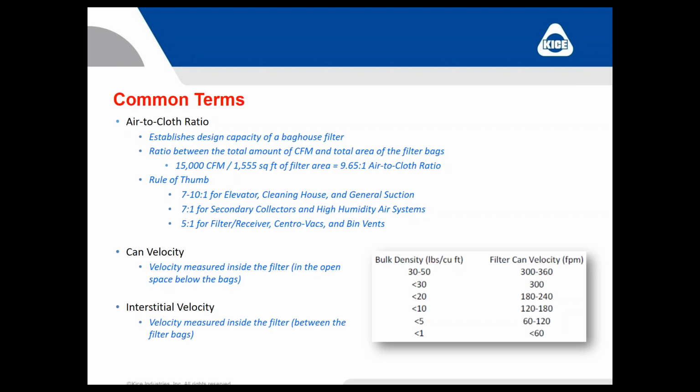I think the standard, and this goes before me, standard used to be closer to 12 to 14 to 1. But people were changing filter bags every 6 months. And then they said, hey, if we have lower air to cloth ratios, we can get away with changing those bags once a year, once every 18 months. And that became more the norm.